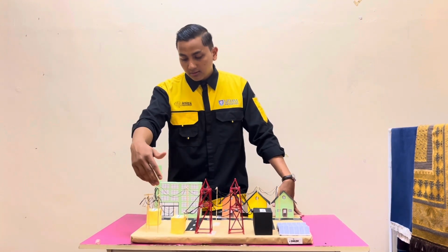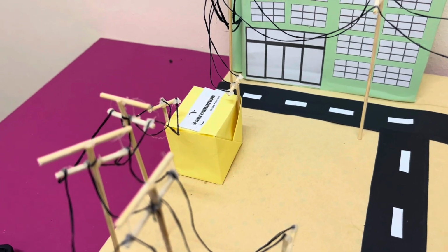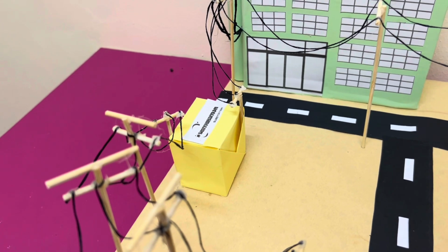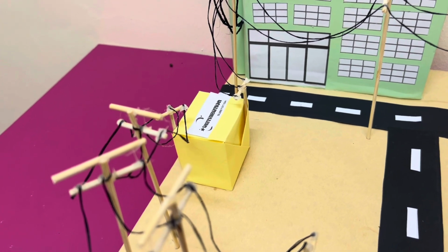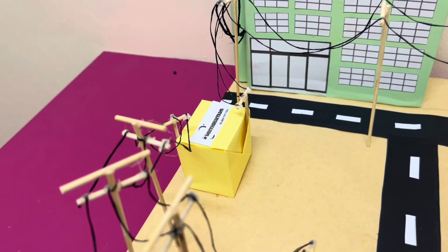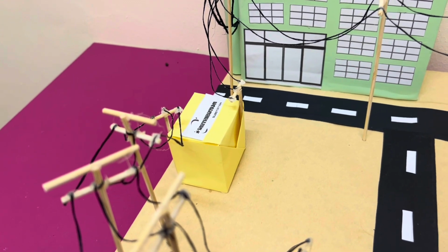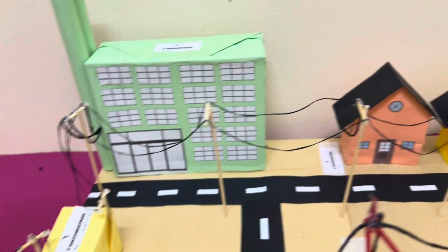And after that, we transfer to the distribution substation. A distribution substation decreases the sub-transmission voltage to a customer usable level. As such, these are also step-down substations like other substations. Distribution substations typically contain a lightning arrestor, overload protector, circuit breaker, voltage regulator, input-output switching circuit, and a control circuit. And the current will flow to the industrial and the residential.